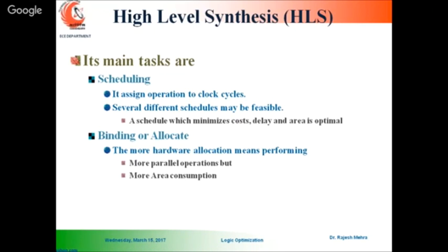Scheduling means assigning operations to clock cycles, and different schedules may be possible. A schedule which minimizes the cost, delay and area is the optimal one. So basically here you have to divide your circuit into different parts.